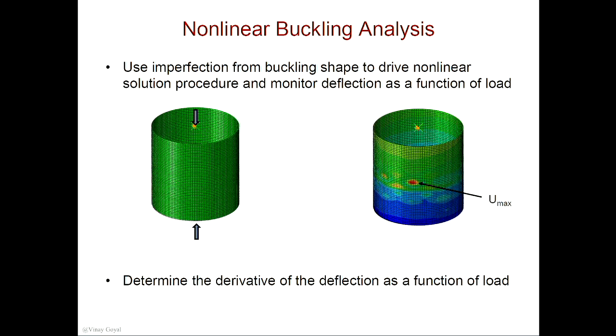So in this scenario, Leonardo will show you, but when you apply a load, you can walk through the steps, and you'll find that there's this one spot that gets hot, and that's the deflection. But you can also monitor other spots as well, where maybe the imperfections start to become worse at that point. The mode shapes that we included, one of the imperfections from the mode shapes is going to make this region buckle maybe sooner than other places, right?